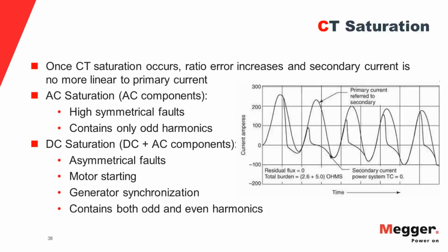This is an example I've taken from the C37 standard, which shows the waveforms of the CT secondary. You can clearly see the distortion in the CT secondary waveforms. And this distortion, if you take the RMS of the current value, could be different coming from both the CTs and can result in the differential operating.